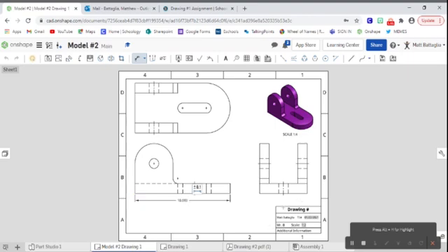Next, let's get our overall kind of width measurement here. So I'm going to go ahead onto our side view and click that corner. And I'll go ahead and click on that corner and we'll drag her down and click. And you can see I got my 5. Now I will have to adjust that out a little bit further later, but it's good for now. And let's get our overall height. So going on to our side view is where I'm choosing to place it. And we are getting our overall height measurement right there.